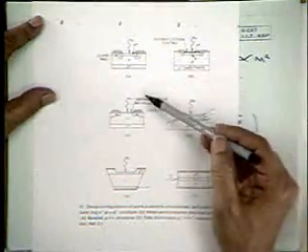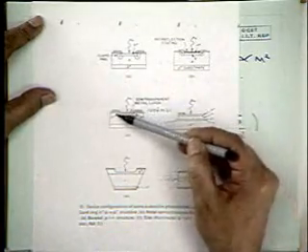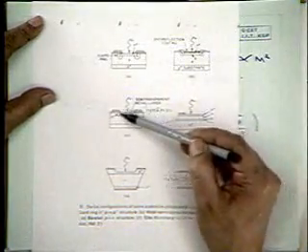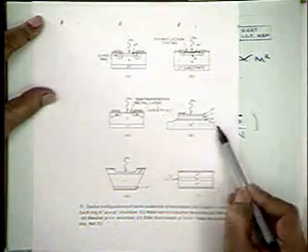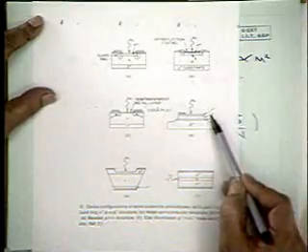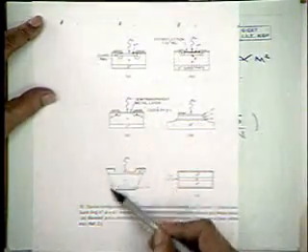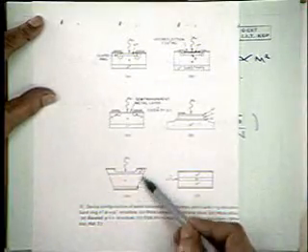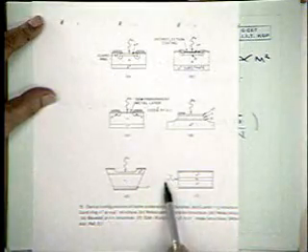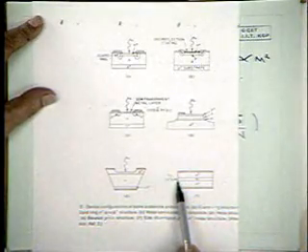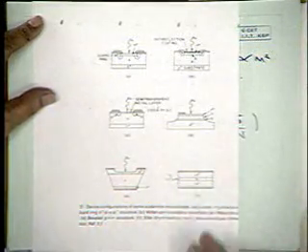Here you have the basic things: guard rings, to reduce the chance of breakdown. If you look at the geometry, this is a Mesa type, N plus N, P, P plus. This is beveled. Why is that? Because then the breakdown field is reduced. And here you have sideways illuminated, like in the PIN diode, sideways P plus and N plus. So these are the standard structures.